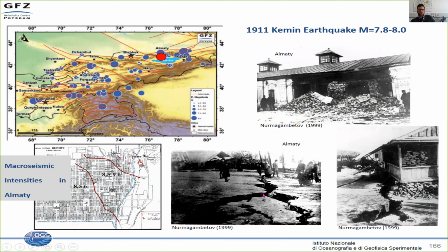So at the bottom of this layer the pressure kept increasing until it liquefied, and then you start having this effect of big failure. You had the greatest amount not in the mountain area, at least as we know, but in this area because you have a river and material that was prone to liquefy. So this can be spotted depending on where the geology is changing.